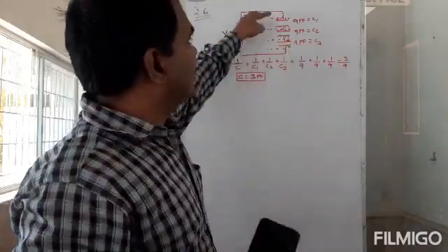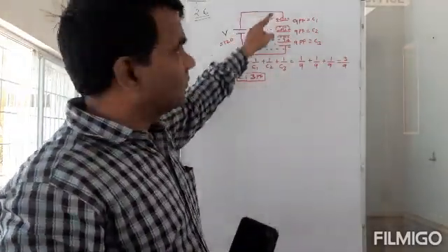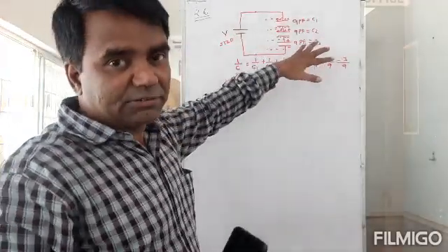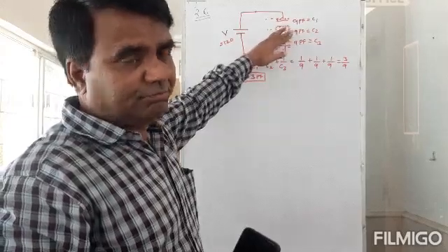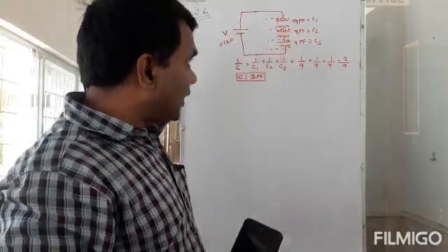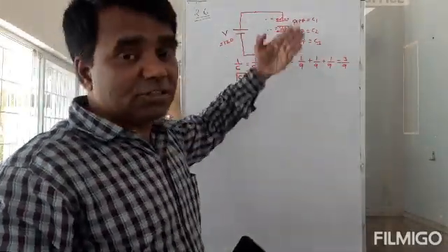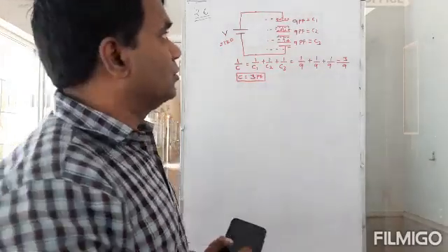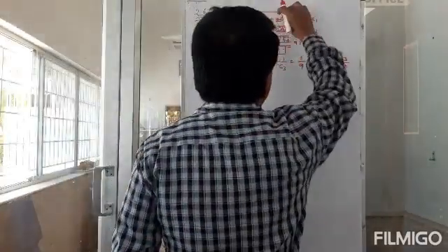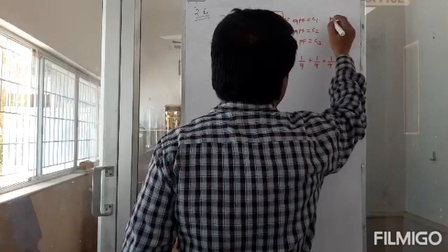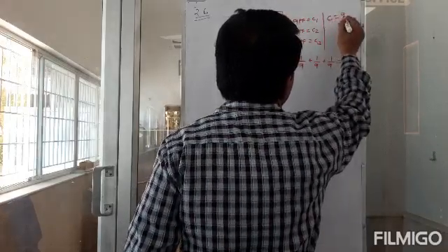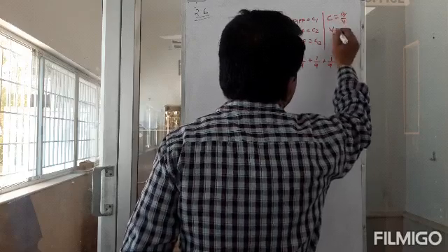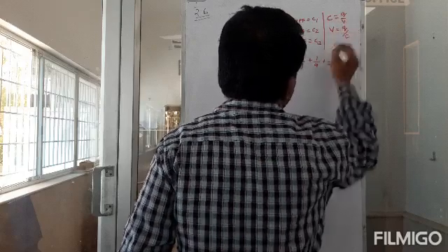You see, all the charges will be equal, because we connected them in series. All the charges will be equal for all the capacitors. And in this case, the capacitance is also the same. So, what is the voltage across a capacitor? The basic expression is C equals Q by V. So, if we want V, we get Q by C.